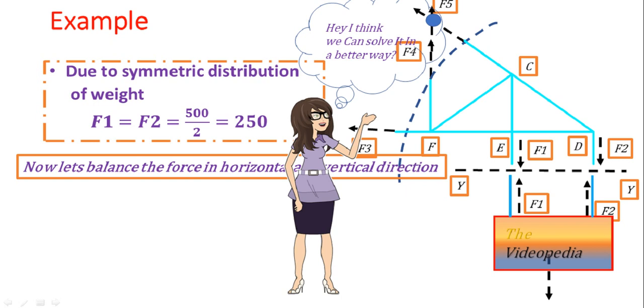Now from moment equilibrium, we know that for static equilibrium the sum of moments about any point must be 0. We are talking about any point, and this is important. So if you take a moment balance about point B, that is the blue dot shown here, we don't have to do the force balance because there is one unknown and one equation. And this is the main reason for choosing this problem.